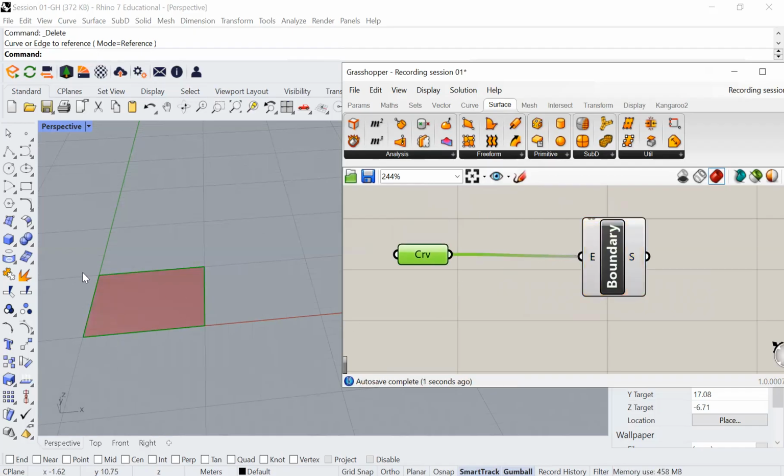and now you can see I have the surface created for me. Don't forget to hover over it, so you can see the values inside. It says in the small box, one locally defined value. That means one curve selected, reference polyline curve, so it tells you what kind of curve has been used, which is a polyline.